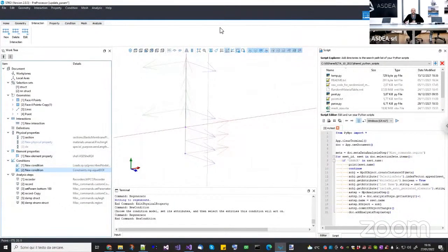Okay, let's see other questions. Then we have Aritra Bagchi. I have two questions, basically from geotechnical background. One, how to capture the force displacement behavior of the zero length contact element, as the new compiled version of OpenSees 3.3.0 doesn't record it? Oh, okay, we are going to check it. I'm not sure about that. Two, suppose we have an embedded concrete foundation and we want to introduce a node-to-node interface element between soil and concrete. Should we give different numbering to mesh nodes for the specific region, only if we create the mesh manually?